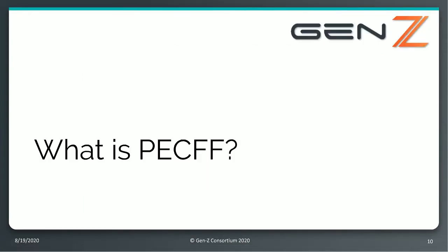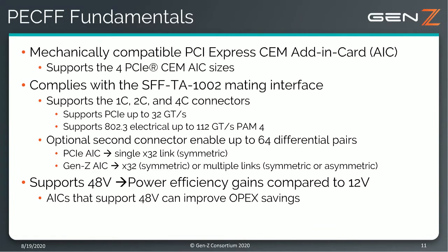Thanks, Steve. So next, we'll actually start to define what is PECFF. Very simply, the acronym stands for PCI Express Enclosure Compatible Form Factor. But what are some of the benefits of that infrastructure? One of the first and foremost benefits of PECFF is it is mechanically compatible with PCI Express CEM add-in cards.